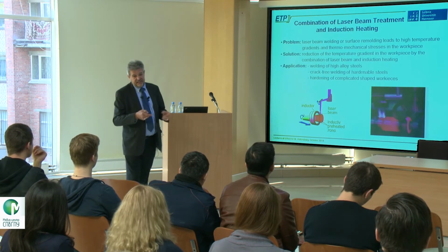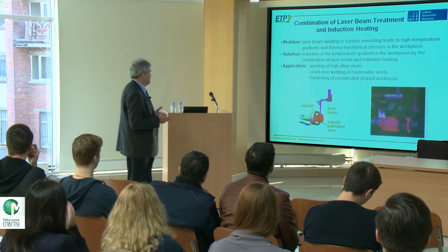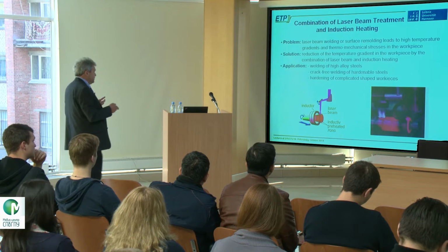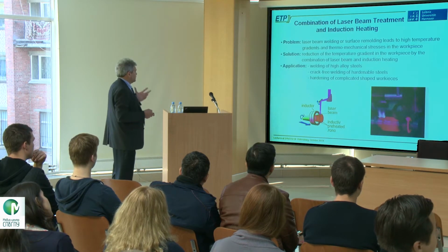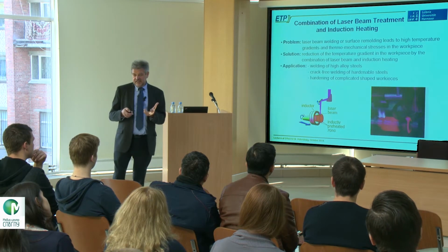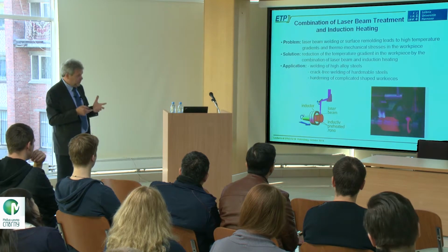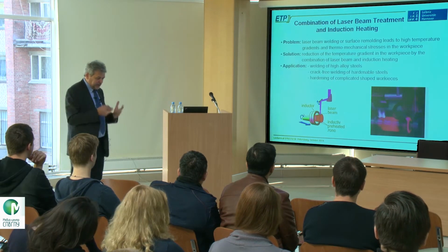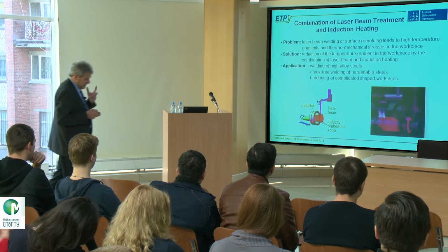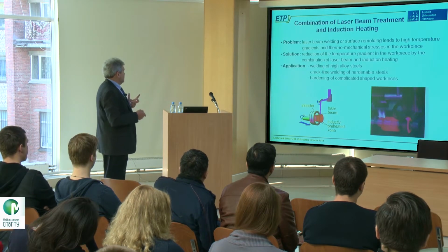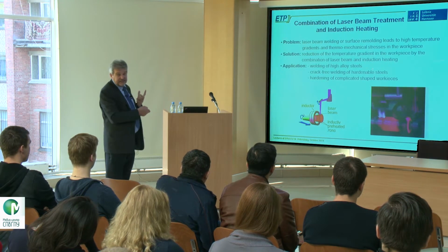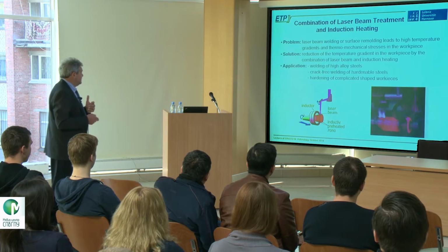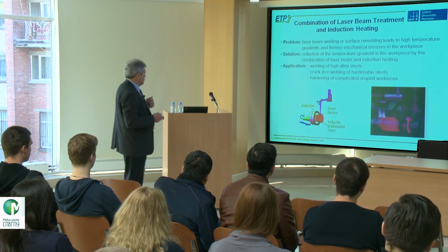Another disadvantage is that laser energy is very expensive, of course, and limited. Power is limited. So the aim or the solution here is to reduce the temperature gradients in the workpiece by the combination of laser with induction heating. Induction heating you can control. It is not so much focused. And then you can bring more heat into the workpiece, into the area where you are welding, and it creates less thermal stresses. So the applications are welding of high alloy steels, which tend to crack, crack-free welding of hardening steels, and hardening of complicated shape workpieces.